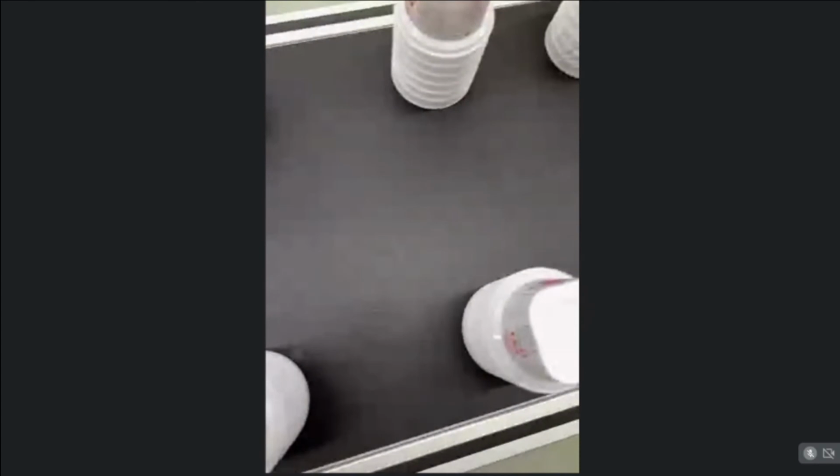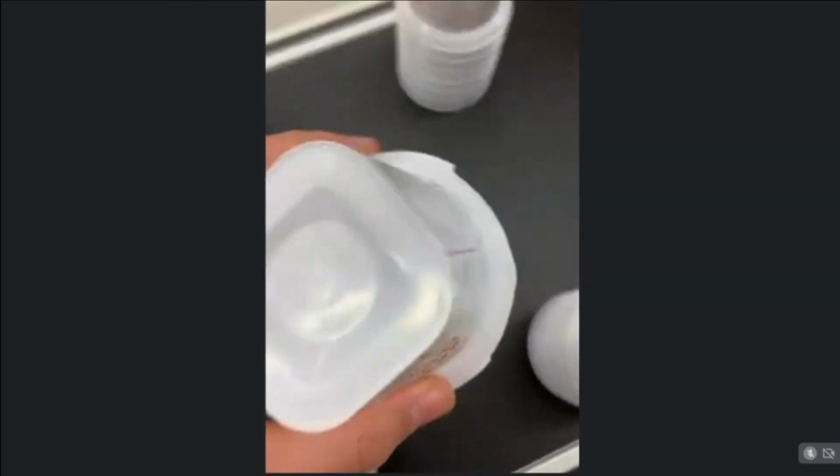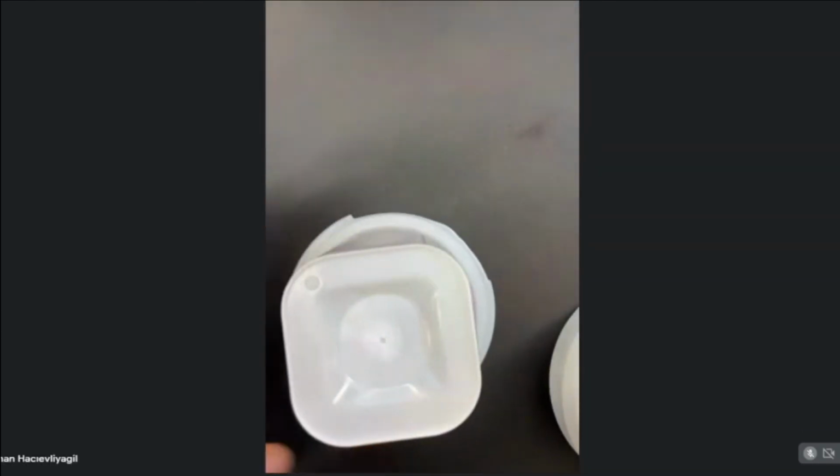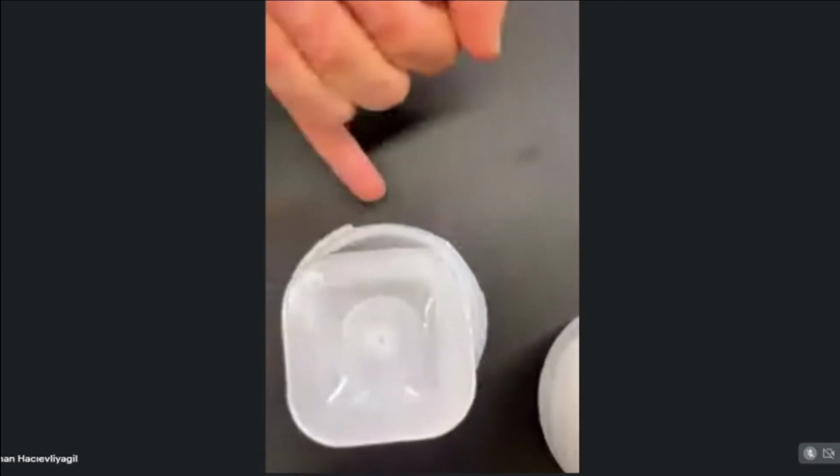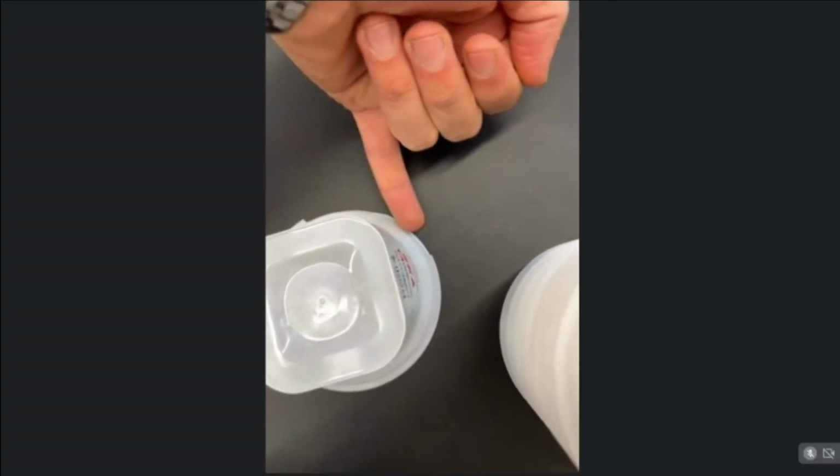But when I see this one, yeah, short run defect. You can see that from here to here, it's material missing. It's not put anymore right. You can also see it like here. So all the cavities are not good anymore.